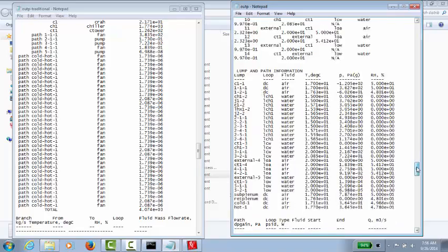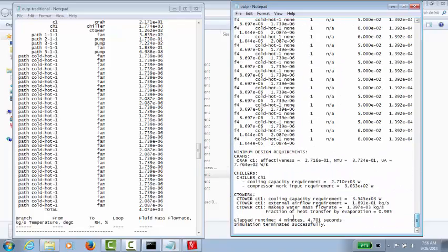Finally, if you go to the bottom of outp, you notice that there is no information regarding the design of the direct liquid heat exchange system. The reason why there are no design parameters for the liquid heat exchange system is because they're provided elsewhere. First, you've already specified the heat removal from the chips, and as far as exergy destruction goes, you've already specified in the server block what the thermal resistance is between the servers and the fluid that cools them down. However, future versions of the liquid heat exchange system may provide some equipment parameters that you could use for the design calculation.